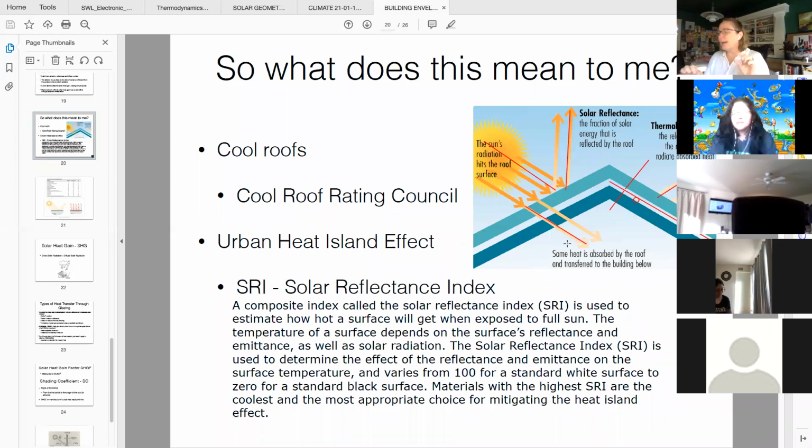They're high performing. However, if you're going to have a cathedral ceiling design on the inside, where it's going to be all open, and the underside of that SIPS panel is going to be visible with perhaps a finished material on top of it, and there's no air gap, there's no space to put in that radiant barrier.